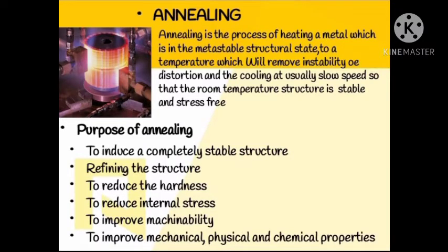Annealing. Annealing is the process of heating a metal which is in a metastable structural state to a temperature which will remove instability or distortion, and cooling at usually slow speed so that the room temperature structure is stable and stress free. Purpose of annealing: to induce a completely stable structure, refining the structure, to reduce hardness, to reduce internal stress, to improve machinability, to improve mechanical, physical and chemical properties of the material.